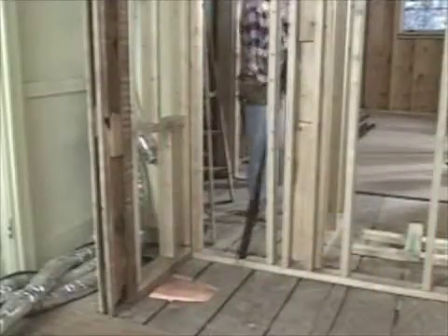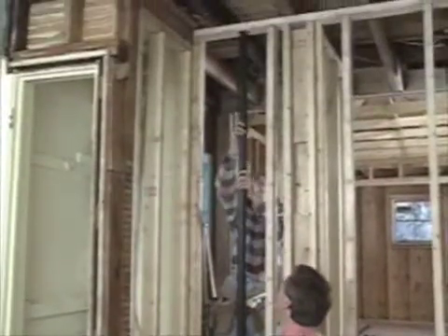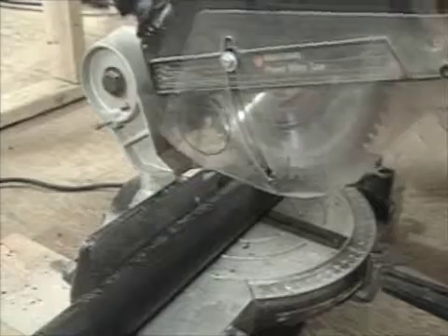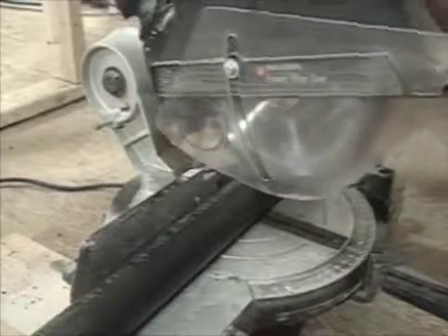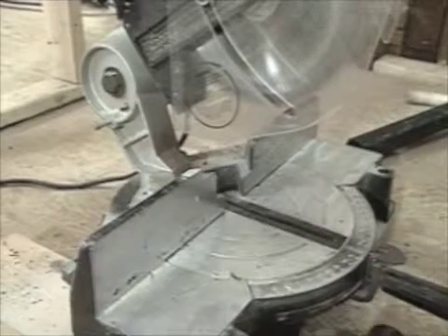There are two types of plastic commonly used for drain and vent pipes. One is known as ABS, and it's usually black. It's fairly easy to cut with a hacksaw, but on a large project, cutting it with a miter saw makes sense for both speed and accuracy. Before gluing, make sure there are no burrs left on the cut pipe.